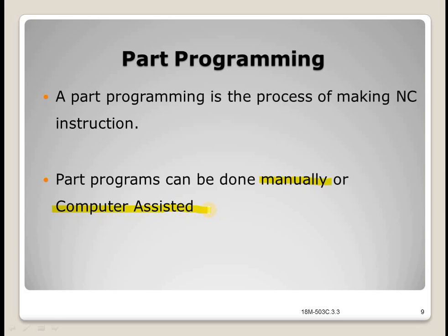Programming is where all the machining data are compiled and where the data are translated into a language which can be understood by the control system of the machine tool. The machining data is as follows: machining sequence, classification of processes, tool startup point, cutting depth, tool path, etc. Cutting conditions: spindle speed, feed rate, coolant, etc. Selection of the cutting tool.